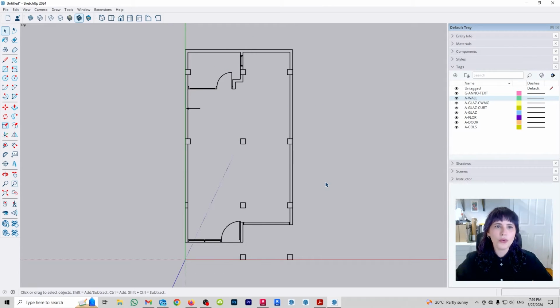Before I start drawing or modeling or doing anything, a very important step that you need to take is to make sure that your CAD reference has been imported correctly. And by this, I mean that it is to scale. This is super important. The amount of times that I've seen people import a CAD reference, start modeling, spend like an hour working on it, and then realize that the dimensions are not working, the math ain't mathing, is astounding. So before you spend any amount of time modeling using this reference, you want to make sure that this reference is actually the correct scale.